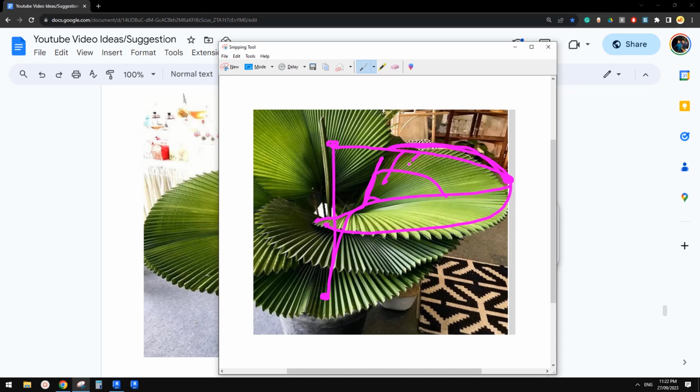Once we have the surface, we can then use divided surface to create these grids, and then eventually we can apply another adaptive point to create this. So eventually we have this shape. Okay, so quite simple, right?